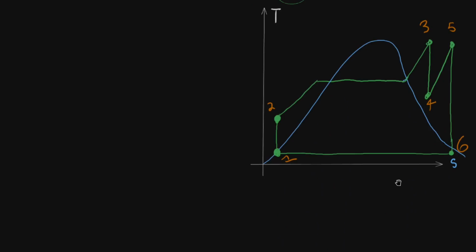So looking at our diagram, pump it, then we're going to heat it up, then we're going to extract work to a turbine down to state 4, then we're going to heat it up again back to the same temperature as what we have up here, then we're going to use our turbine to extract work, and then we're going to come back here. You can see this increases the area of the shape, which is going to give us more network output, ideally.